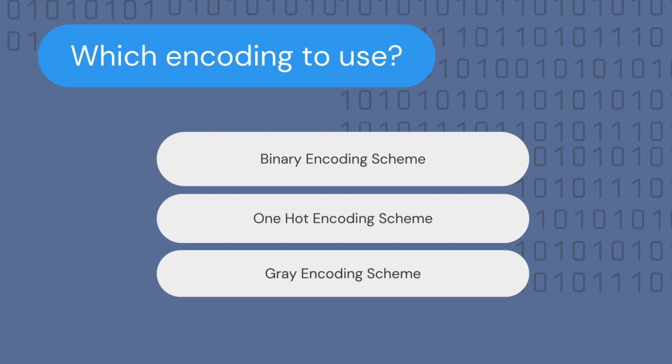However, when we start writing code with VHDL, we don't have to worry about this. As we will see with the syntax, we don't really need to encode things using one-hot encoding or gray encoding, but rather we can create different states within VHDL's architecture to represent the finite state machine.